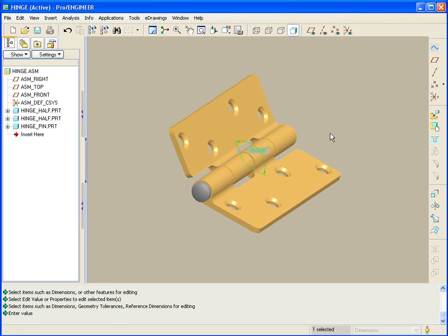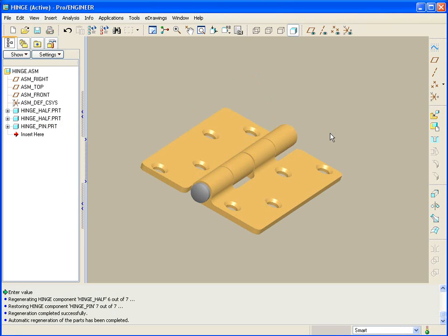Now, why wouldn't I set a hinge up as a mechanism in this case? Well, a hinge as a mechanism applied to a mechanism that's already in place would have redundant connections, which would likely cause performance impact or perhaps even cause the assembly to fail. So I would leave those out, especially since a hinge would be an assembly of its own that would likely be off the shelf or maybe part of a family table that you'd like to replace.